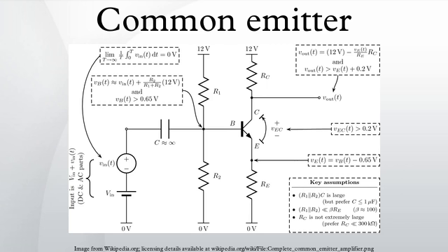This configuration holds the transistor's collector voltage roughly constant, thus making the base to collector gain zero and hence removing the Miller effect. Another option is using a differential amplifier topology, like an emitter follower driving a grounded base amplifier. As long as the emitter follower is truly a common collector amplifier, the Miller effect is removed. The Miller effect negatively affects the performance of the common source amplifier in the same way.